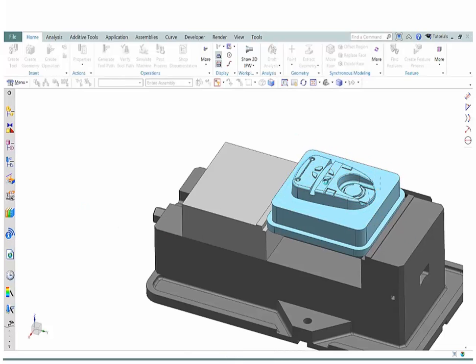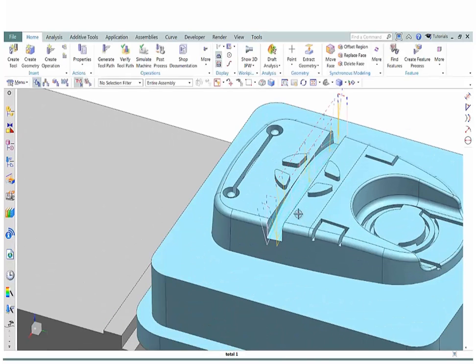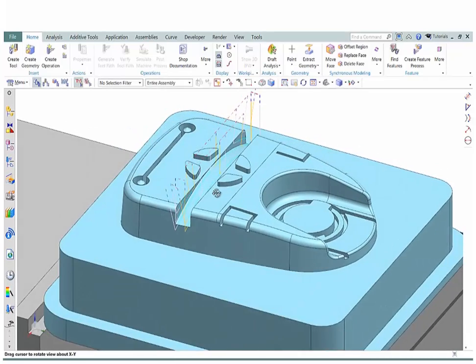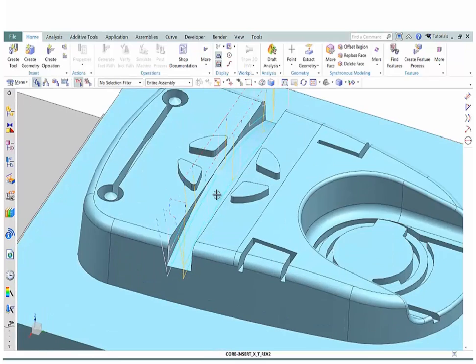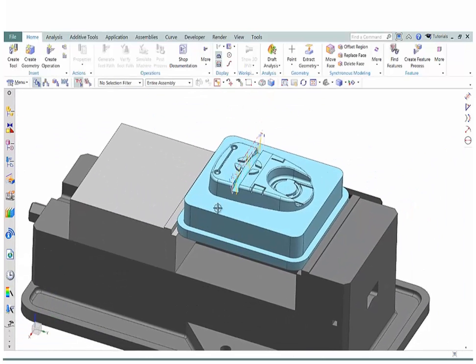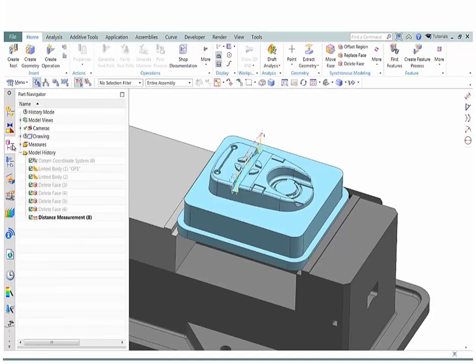And then it's going to take a look at all of those changed areas. And we're going to take a look at what happened with that tool path in that area, particularly with the slots and on the face milling. Those little bosses have moved. So there you see on the slots, a great example of that. It just literally added the additional passes for you. There's nothing else to do. The topology for the part has been updated, so all those tool paths have been done. You don't have to reprogram the part or make any other changes.